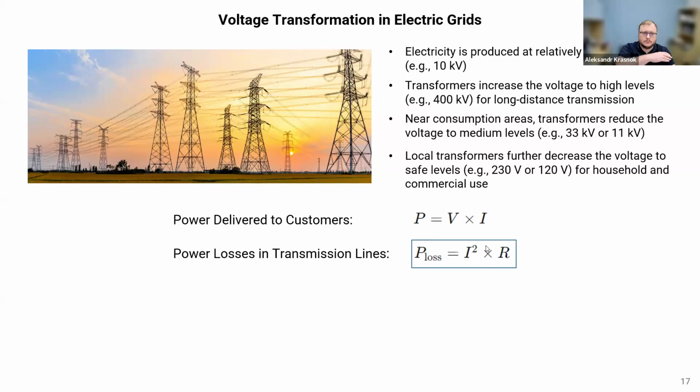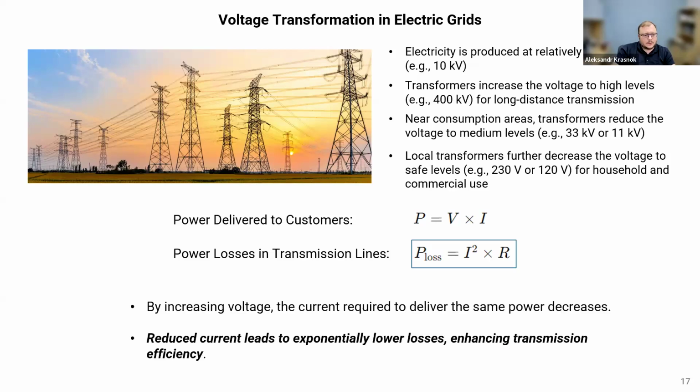If you increase the current by a factor of 2, right, the consumed power is increased by the same factor, by 2, but the loss power is increased by a factor of 4. So increasing current means you lose more to heating. So the way to make these lines more efficient is to reduce the current in the wires, okay, using transformers.